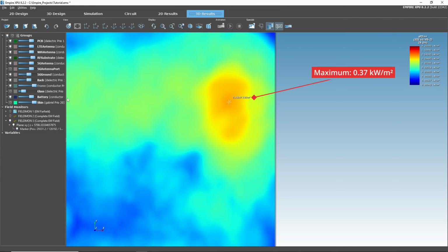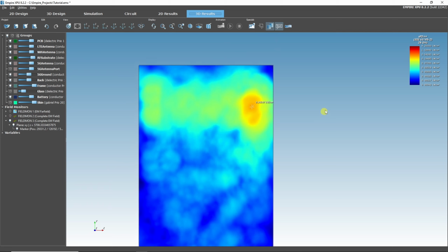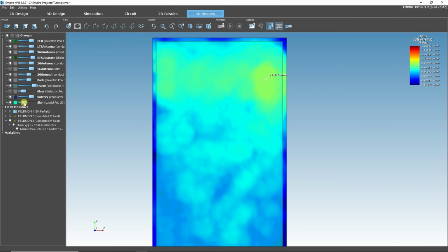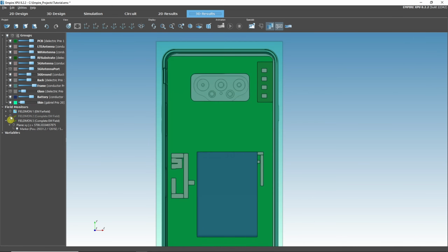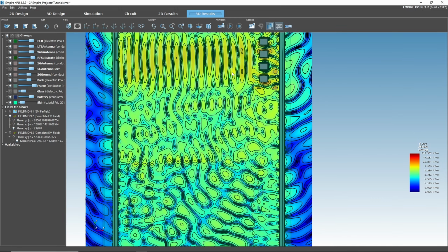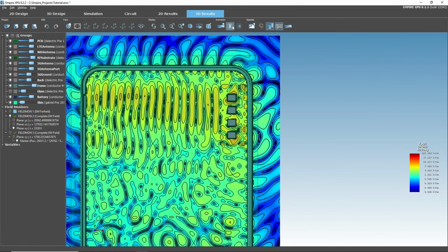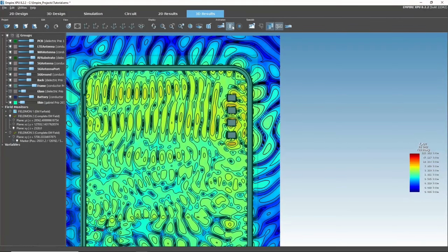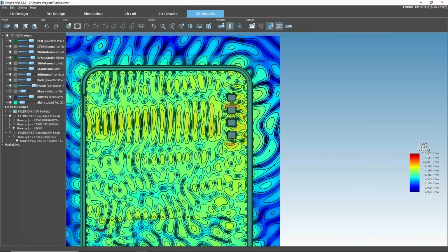As a final step, we will look at the near field of the antennas. Change the transparency of the skin box and activate Field Monitor 2 instead of 3. Initially, focus on the XY plane. While the pattern bears resemblance to the configuration before integrating the flat phantom, a notable difference emerges. The electric field is substantially stronger.